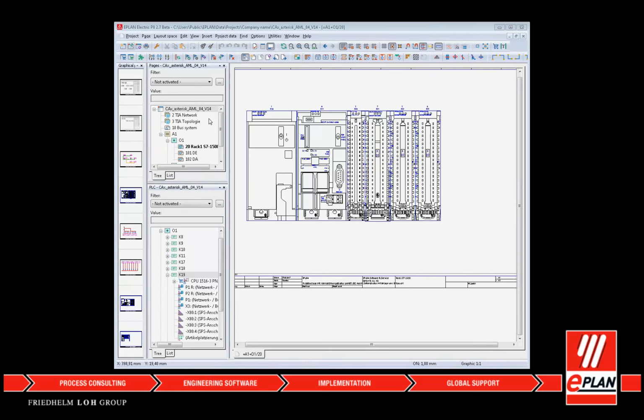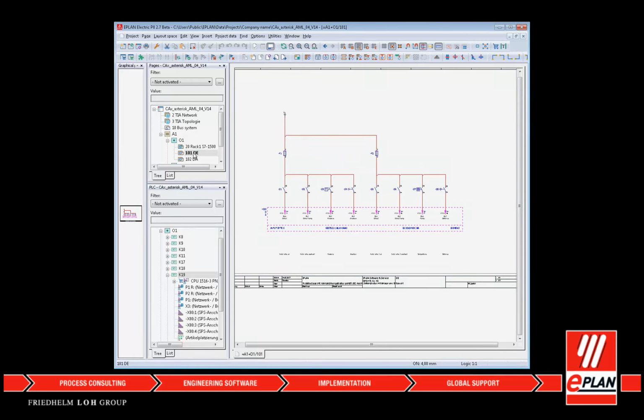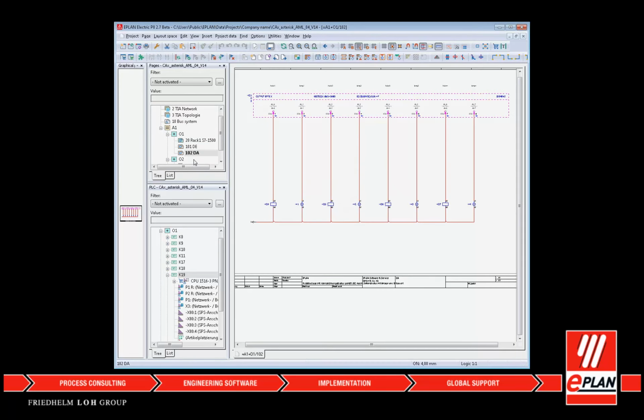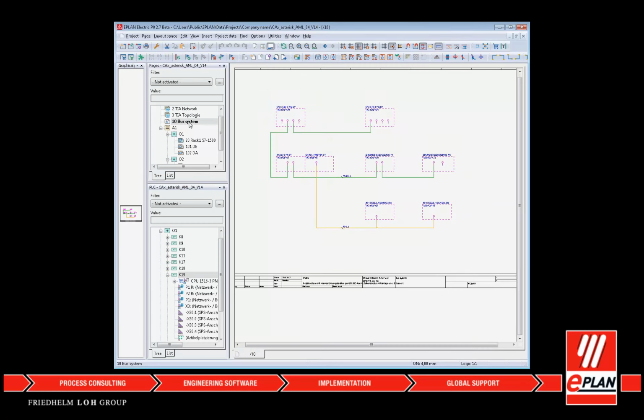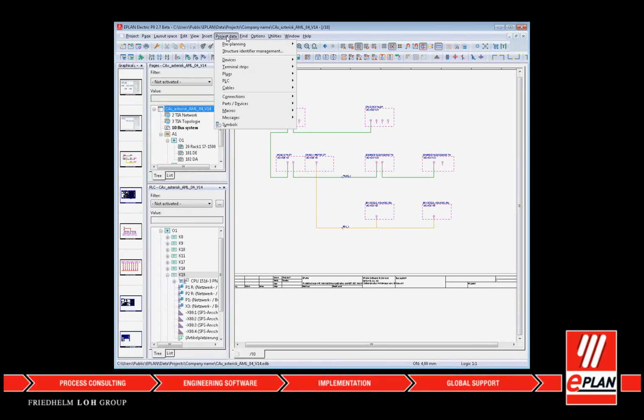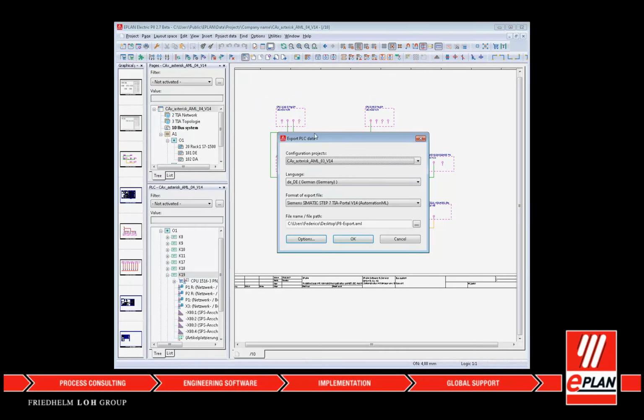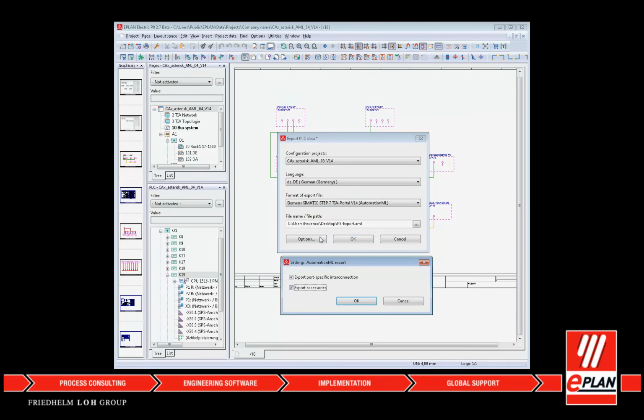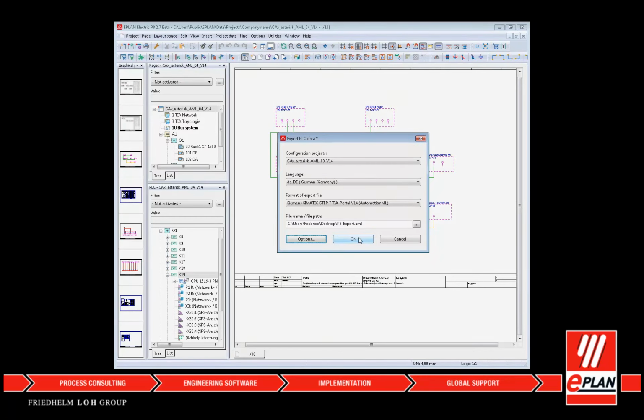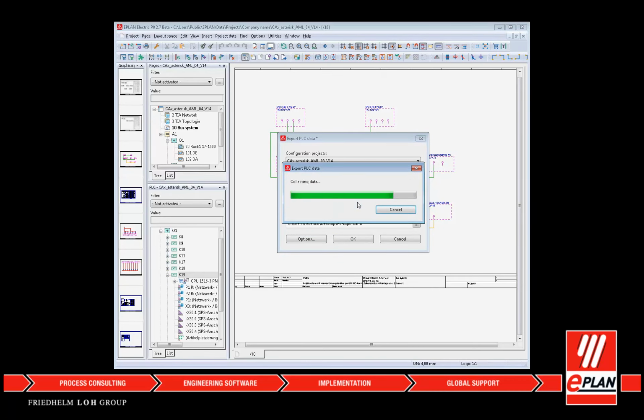Each object is identified in AutomationML by a GUID, globally unique identifier, that is unique worldwide. This GUID is assigned automatically during the export. The names of the modules within a rack have to be unique for the export in AutomationML format. In this case, the object description is not exported as the name, but rather the module name property. If the module name is empty, the object description is exported and, to make it unique, a consecutive position is attached: description 1, description 2, etc.